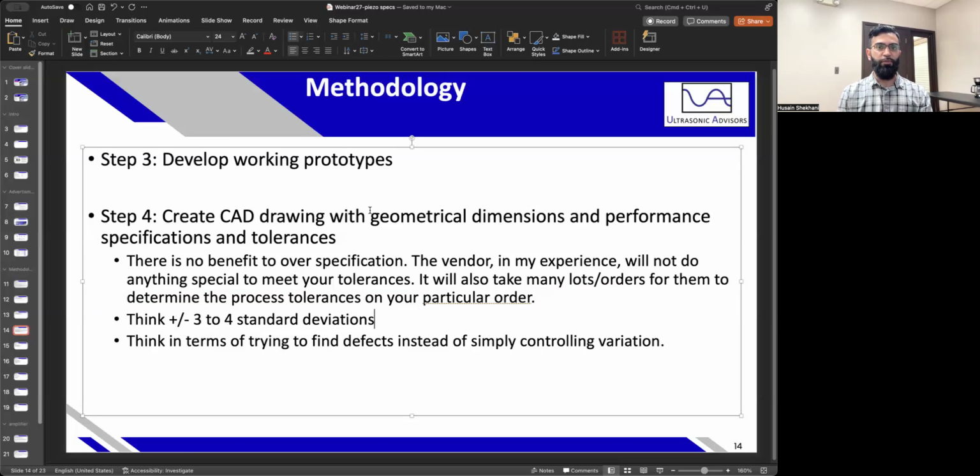And some aspects like geometrical dimensions you can control much more closely, and also frequency, but the coupling factor sometimes and the charge coefficient does vary, and also capacitance significantly can vary. But these parameters are all related. So typically when your capacitance increases, typically the coupling factor is conserved. And if you know what the coupling factor consists of, basically if you have a higher charge coefficient, generally your capacitance will increase, which will kind of not allow your coupling factor to change too much. So it kind of conserves itself.